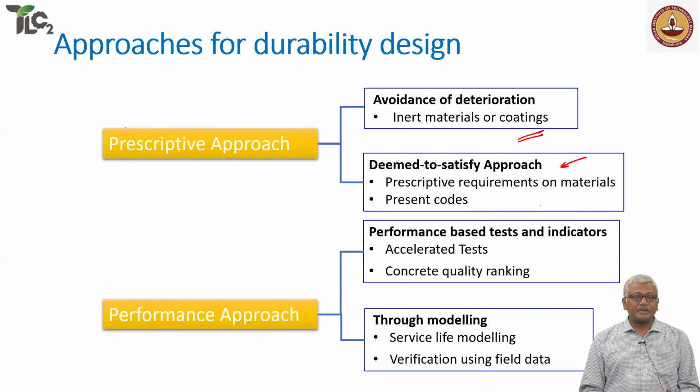Or sometimes we use coatings, right? Coatings for the concrete or the steel can also be used in most codes and most design strategies. These are called additional protective measures, APMs, right? APMs can be used in addition to designing concrete for durability, but they are not the only guard against deterioration